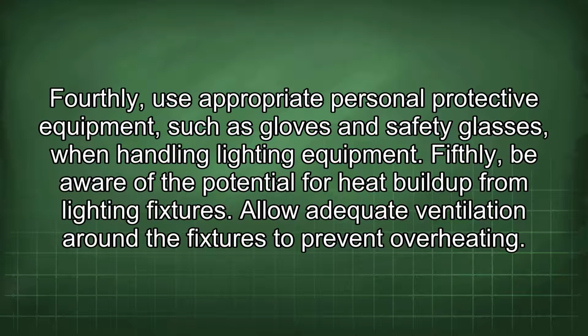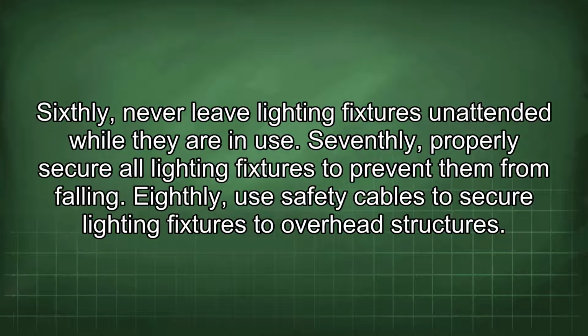Fourthly, use appropriate personal protective equipment, such as gloves and safety glasses, when handling lighting equipment. Fifthly, be aware of the potential for heat buildup from lighting fixtures. Allow adequate ventilation around the fixtures to prevent overheating. Sixthly, never leave lighting fixtures unattended while they are in use.